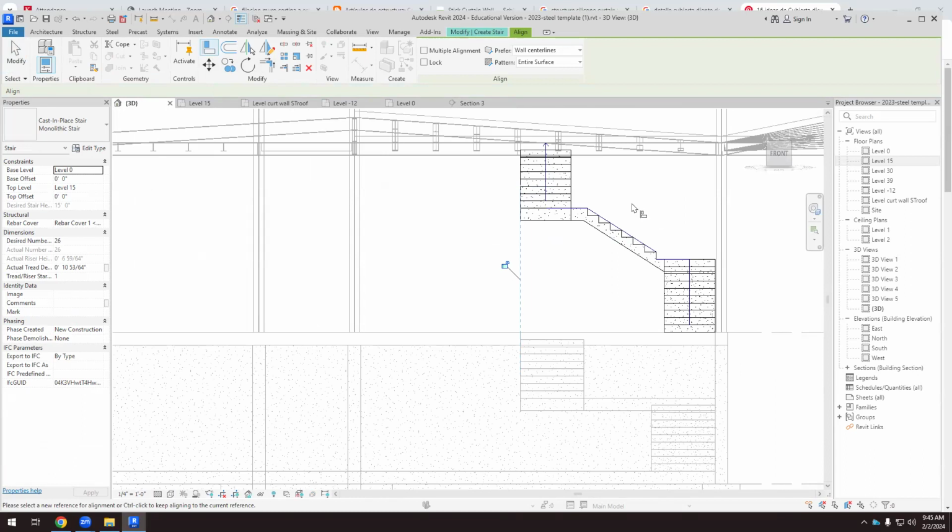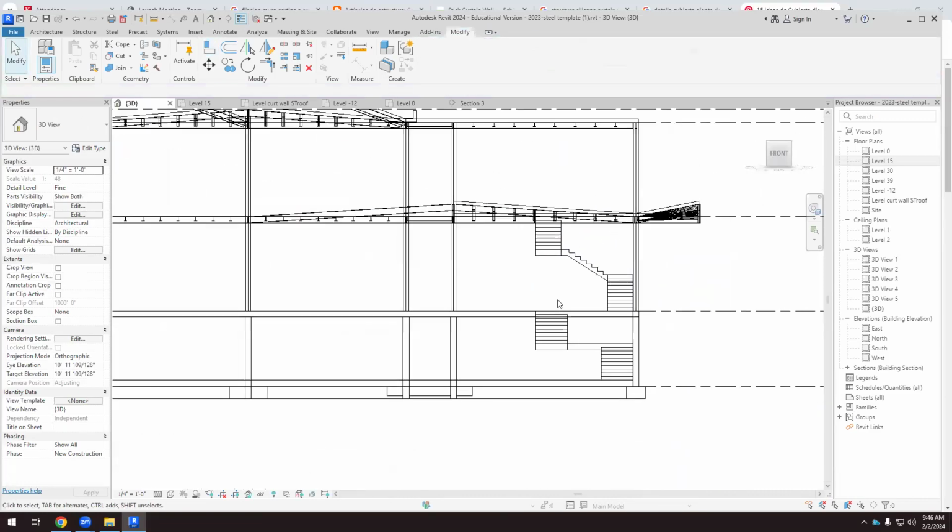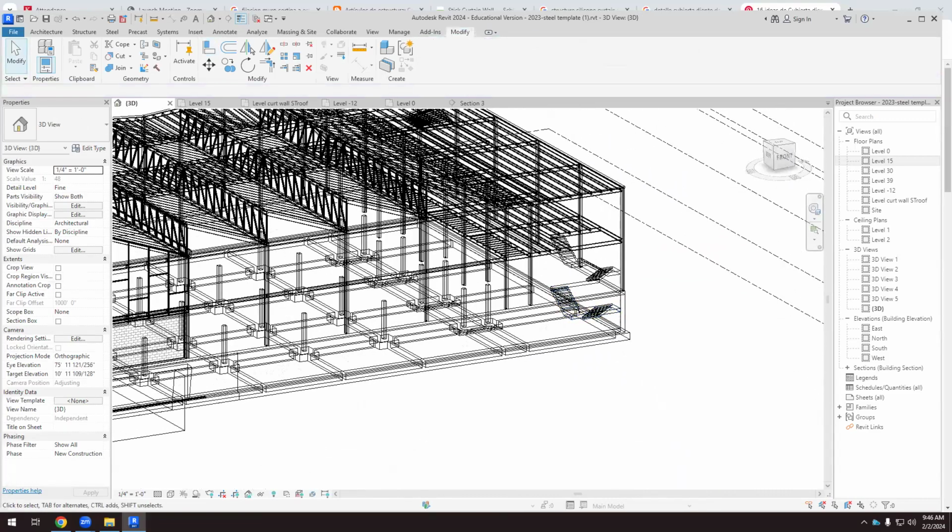What I did before, I lined things up without selecting edit stairs, and that moves all the stairway either leftwards or rightwards. If I want to move only this run, then I have to edit stairs, and then I have to line things up. Okay, so now it works, I think.